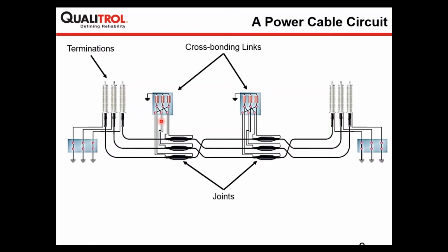So whenever a cable transmission network is laid out or the circuit is designed, these cross bonding links are placed at different joint locations to minimize the effect of circulating currents or the induced current which travels along the cable earth, and then actually increases the cable temperature.